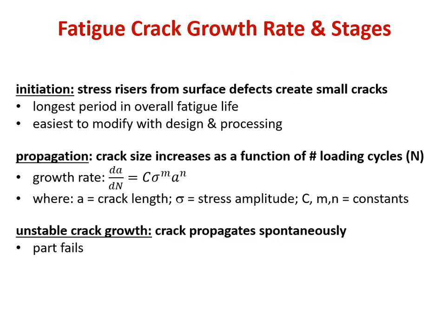Things you can do there: keep surfaces smooth, prevent surface defects, harden or put the surface in compression. We'll discuss a couple of techniques to do that.